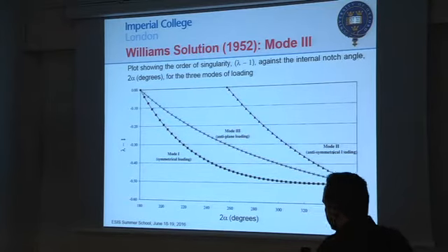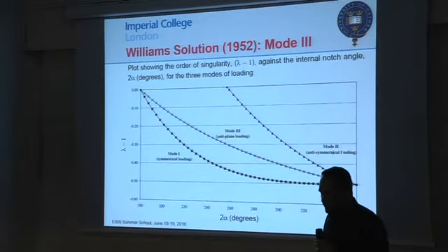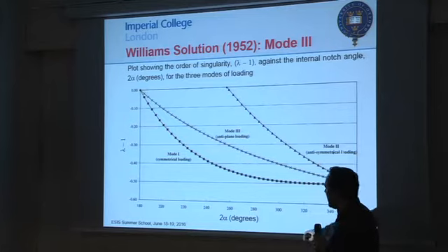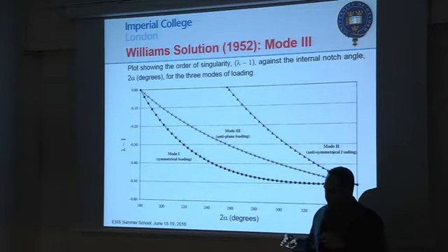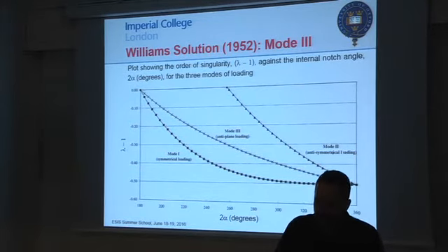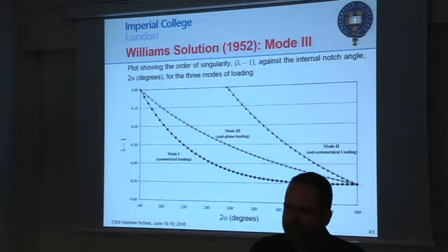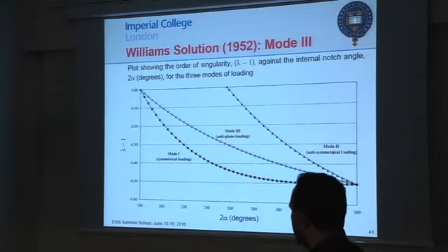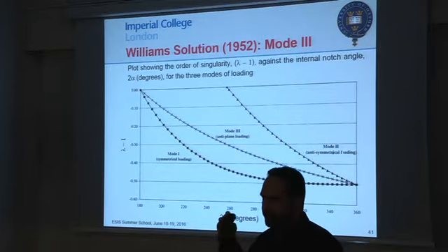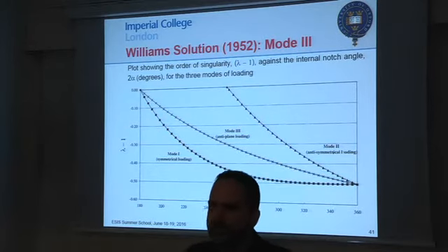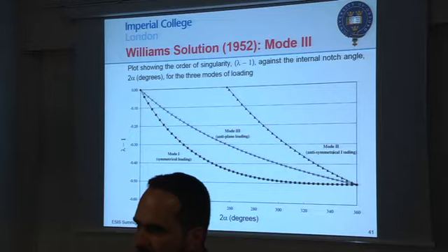So the idea is though that now we've done all three modes, and for them we know that we can write the stress field, if we apply mode 1, mode 2, and mode 3 loading, as a sequence of three terms. There's going to be the mode 1, K1 term, plus the K2 term.